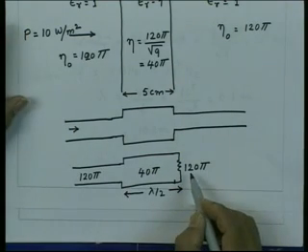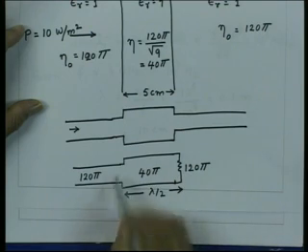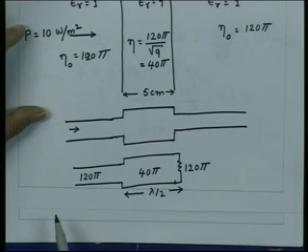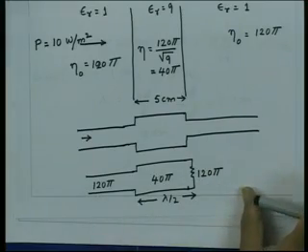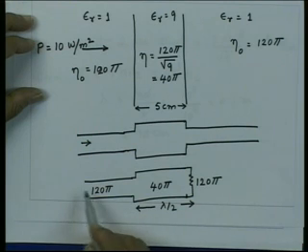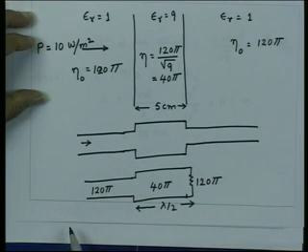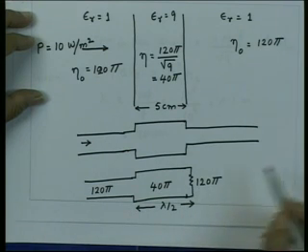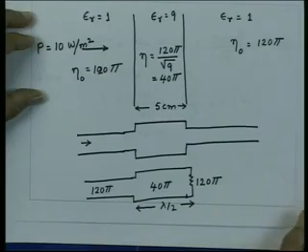So, essentially we can calculate this impedance and transform it to the other side. You get the impedance which is 120 pi on the other side. Once you get that impedance which is transformed here, you can find out the power which is delivered to this load, and from there the power density which has gone to the second medium. That is one approach.